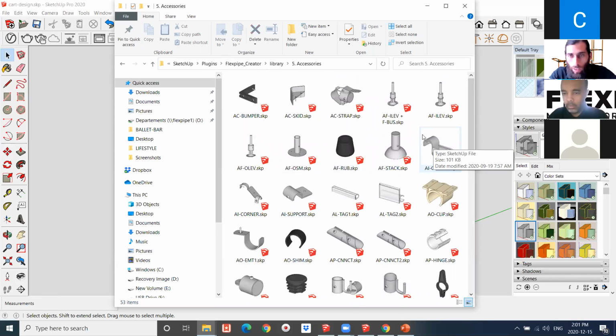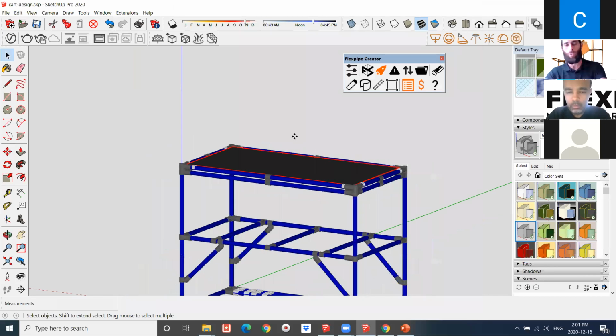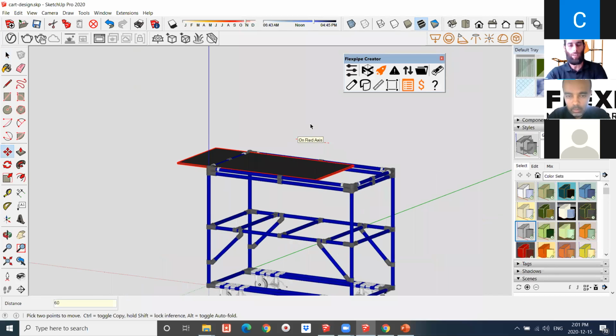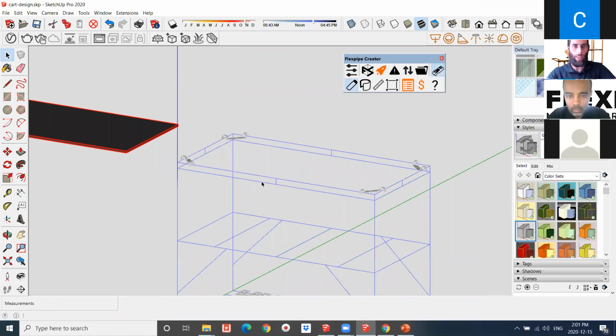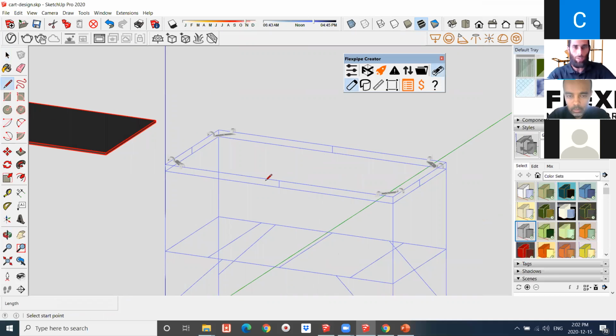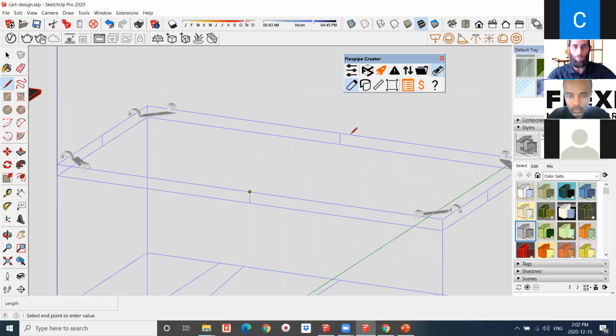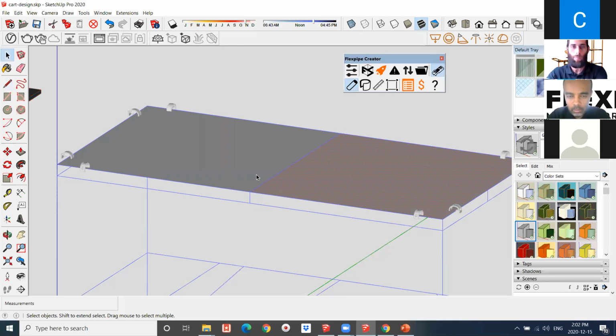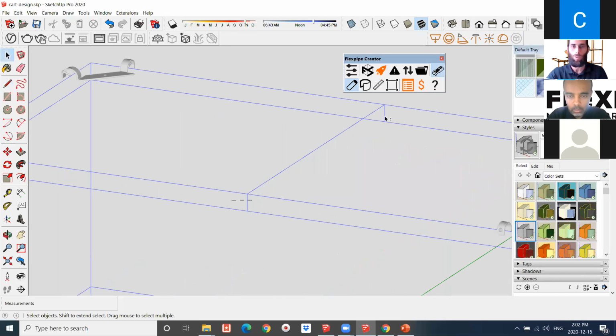The beauty is the line drawing: we draw that line, and we will be able to connect that AI center once we draw this line in the middle. So I'm going to put it in the middle there, and then copy these over and move them out of the way, let's say 2.5, just to have enough clearance from the actual pipe that's going to be placed there.